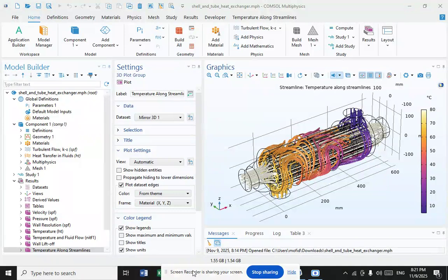The driving temperature across the heat transfer surface varies with position, but an appropriate mean temperature can be defined. In most simple systems, this is the log mean temperature difference. Sometimes direct knowledge of the LMTD is not available and the NTU method is used.